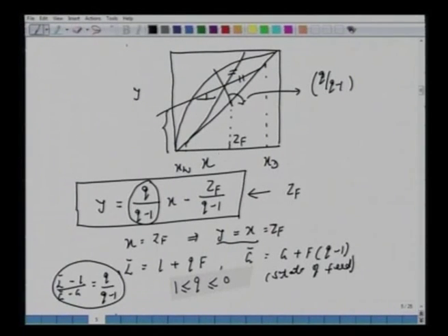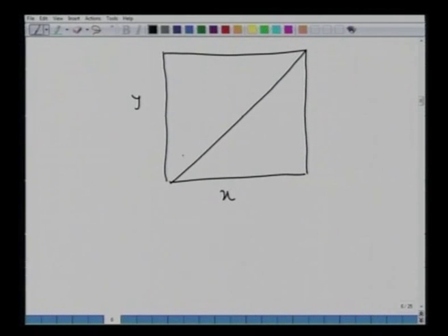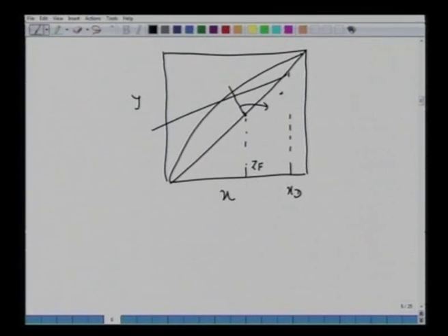All right. So what does it mean? If I redraw this, the equilibrium curve, y versus x, the 45-degree line, and now what I do, I start with xt, take the slope of R by R plus 1 or intercept of xt by R plus 1, and then I take this ZF, and draw this Q line with the slope of Q over Q minus 1.